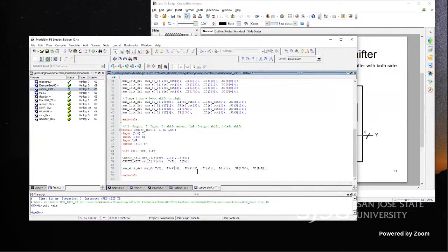And also note, there's a notation 4'd0, where D means decimal, followed by the values, so it's basically a decimal value. Whereas this tick B means that the digit pattern that follows is a binary pattern, not a decimal pattern. But anyway, that's a side note.